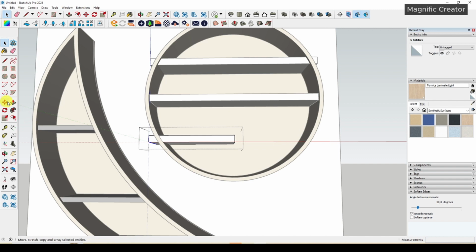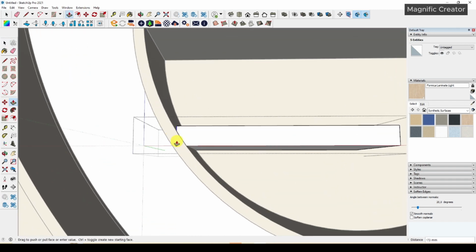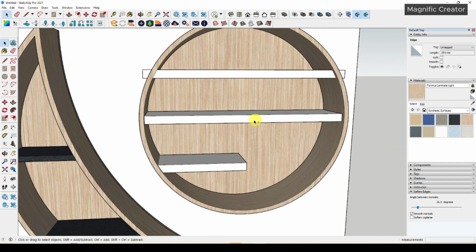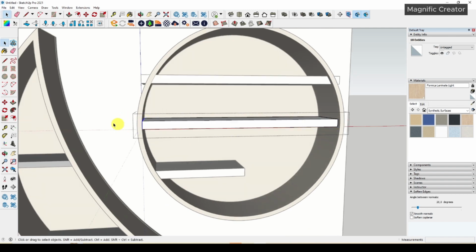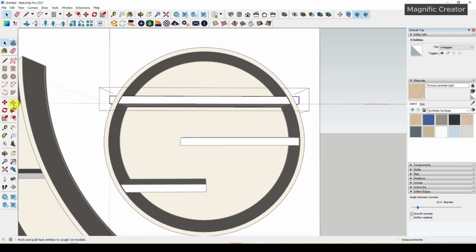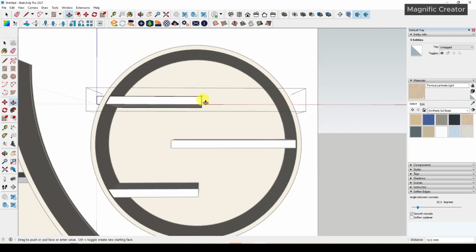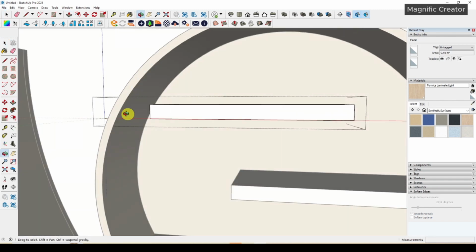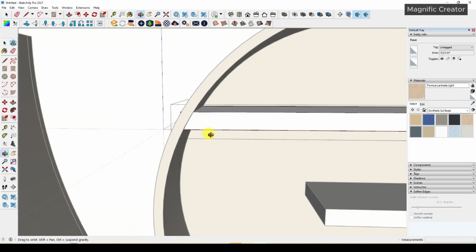Make sure that the end of the shelf is in the correct position inside the circle cabinet, circle shelf, I'm sorry, like this. Then you can adjust this by just selecting this end of the shape and pressing push and moving it to the right side, and this one you also have to move to the left side, so it would be a dynamic arrangement of the shelf.